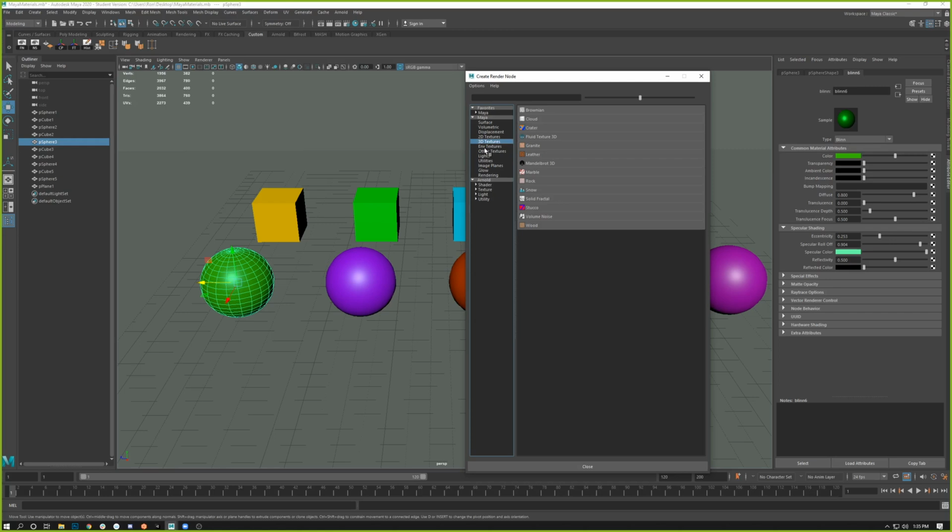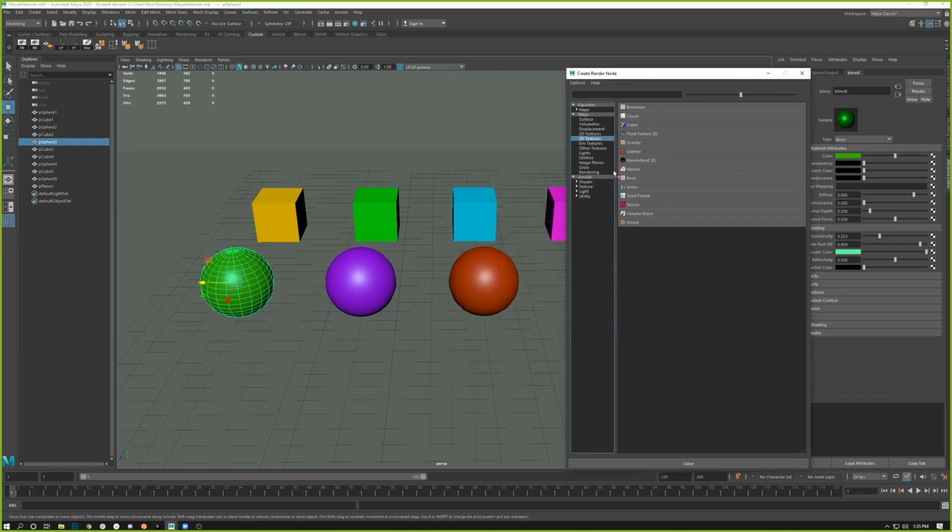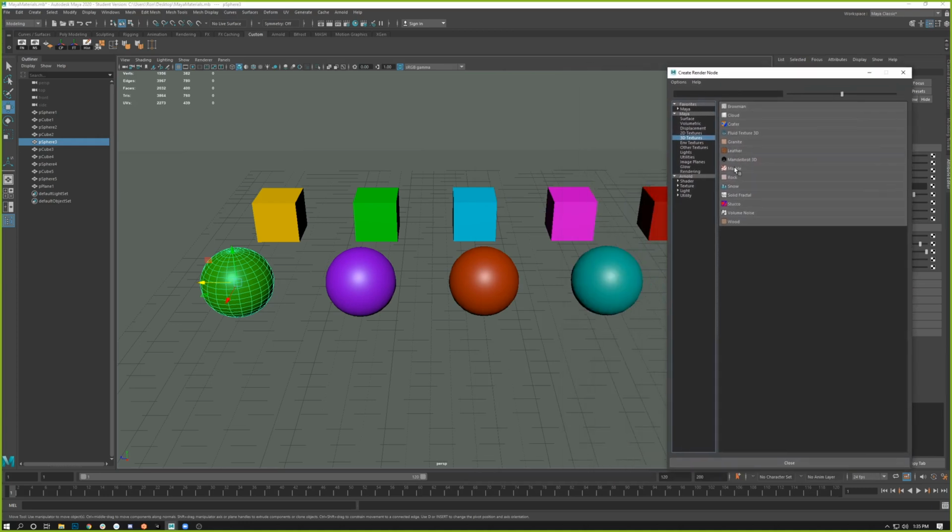So again, I'm not going to be able to cover all these, but let's go ahead and pick one or two of these to start out with to get going. I'm going to pick 3D texture, and I'll pick marble and try this one out for you guys. Now, whenever you do a 3D texture, the first thing I want to note is that it's going to create that projector that I mentioned in your scene. So you have to be on the lookout for that. And by default, Maya always puts the projector at the origin, the 0, 0, 0 space. So if you have things in your scene, just know that it might be buried underneath there.